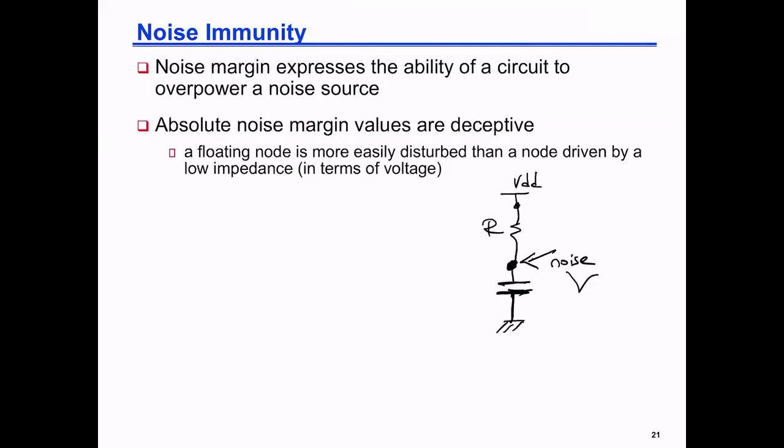So it will send current from VDD to recharge the capacitor when the noise goes away, right? If the noise pulled charge from the reservoir, the resistor will charge it again, based on its time constant. If now I have all of a sudden opened the link, and let us say that this was VDD here, or some source voltage here, I opened the switch and I had previously charged the capacitor. It was charged.